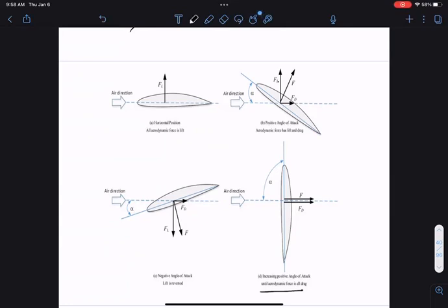Every wind turbine we use has to be tested in practice in the field. When they test your wind turbines, they really don't test how much power you can generate, how efficient you are in generating power. That's sort of not their problem. What they test is, can you stand up to high wind speed? Can you lock your blade? Locking the blade means you're generating no lift, it's all drag. And can your tower stand up to this kind of force? So that's where they physically test all those things.